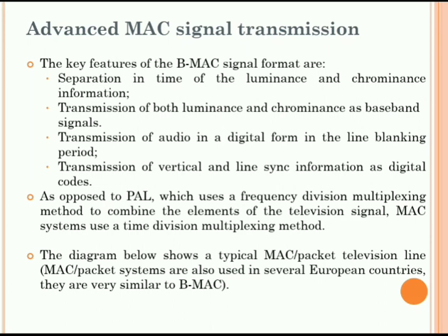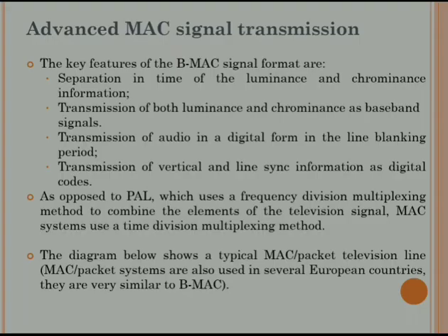The programmability feature of the MAC video and synchronization system also has the advantage of flexibility for future changes and improvement in television technology. The MAC processor produces all 625 lines on each scan instead of an interlaced scan, so that a higher definition picture can be displayed here. The component coding has the advantage of changing the required video formats in the MAC. These are the advantages of the MAC technology.